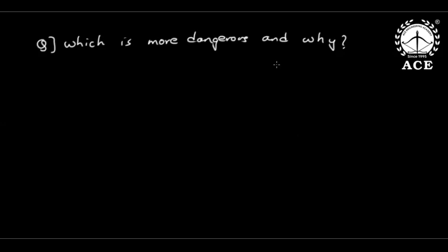No, sir. Short circuits actually will allow more dangerous current to flow through the equipment. But if you have fuses and circuit breakers, you can always protect them. Please understand this. Short circuits are always easy to protect, because any dangerous short circuit current can be protected by using proper fuses and circuit breakers. But open circuits in high voltage engineering are not so easy to protect because of insulation problem.